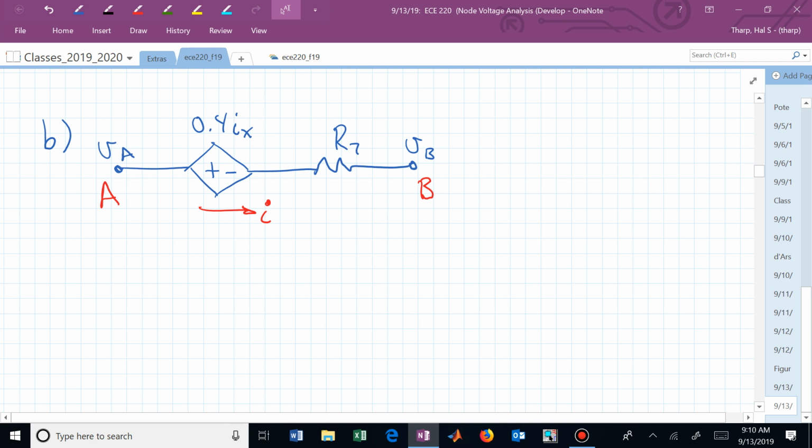Yes. Well, the total voltage across everything is VA minus VB, and you know that you're going to have additional, I guess, dissipation power at that independent supply there, so you can basically subtract that from the VA minus VB. Did everybody get that logic or hear that logic?